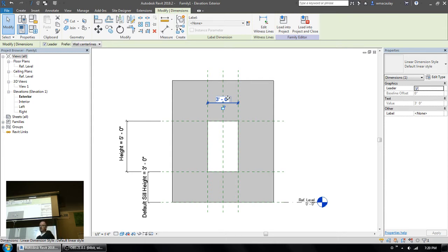With windows, it's a pretty straightforward process, but with doors, of course, we need to take that door leaf and glass and ensure that the 3D geometry still appears in 3D, but is hidden in plan. So you'll see that in practice in just a few moments. So that's step 7. So that's where we add the two-dimensional geometry as required. Now this window won't require it. So let's go over to the next page here. So we'll just talk about the different basic modeling tools that Revit provides.